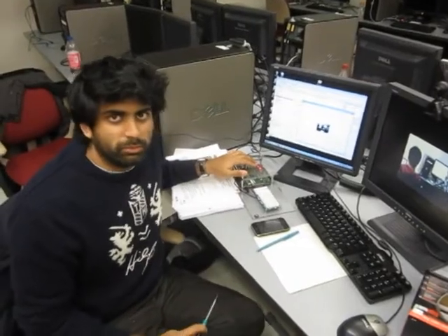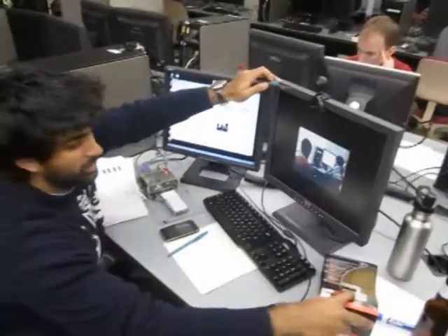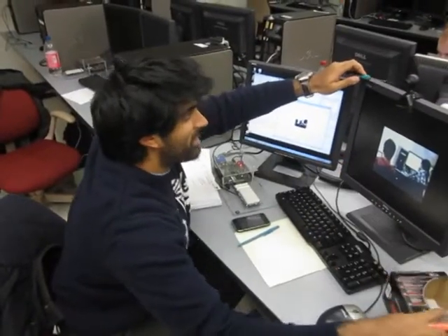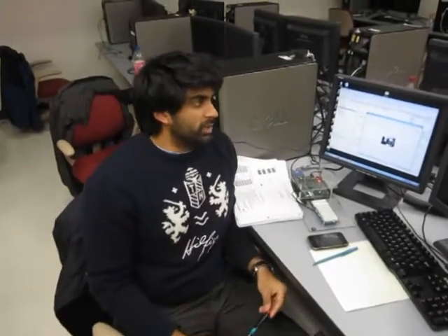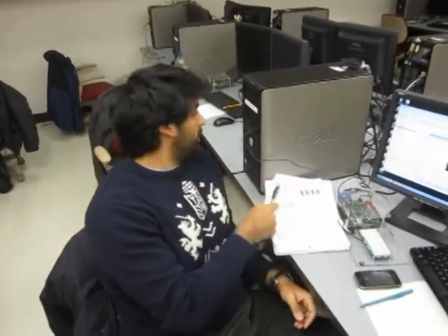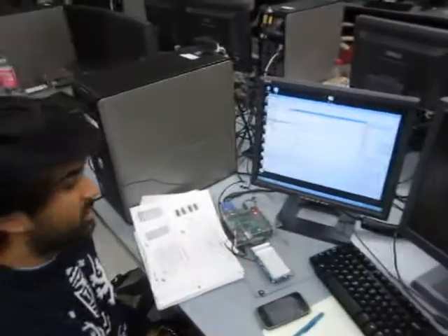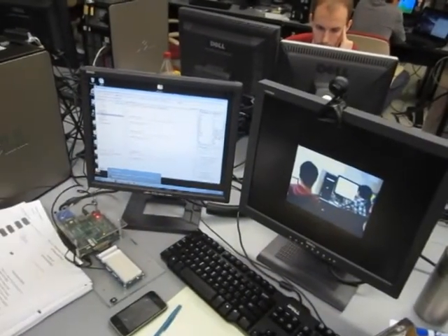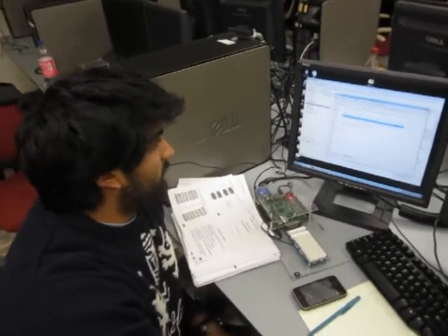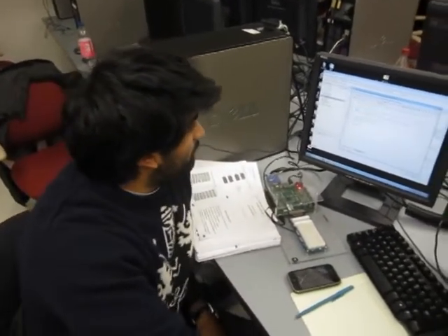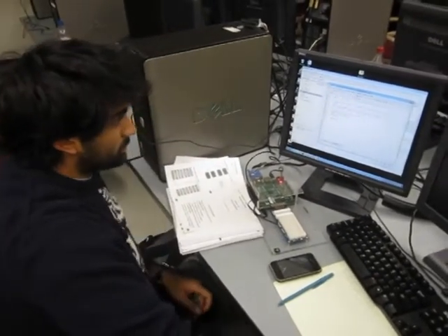Through our top-level system design, it all begins at our USB camera made by Gigaware, which outputs a 160 by 120 RGB image over USB to our Windows PC, where we use MATLAB to process this. We have two MATLAB scripts, the first of which is the initialcam, which initializes the serial port and the camera.